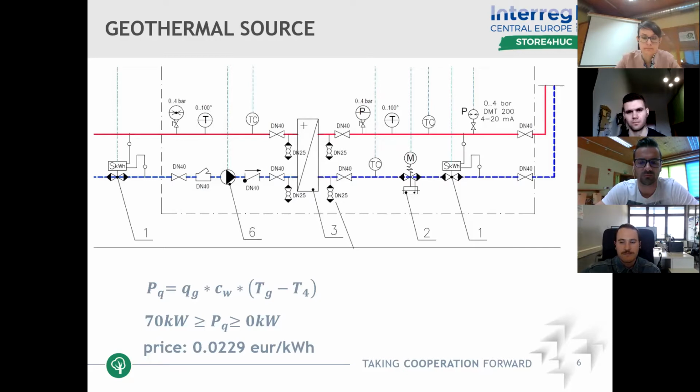It is very important for the optimization to presume this temperature profile available on the primary side, because that's what then gives you the advantage in predictive control to take out the energy when it's available,